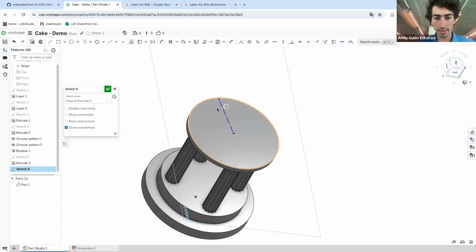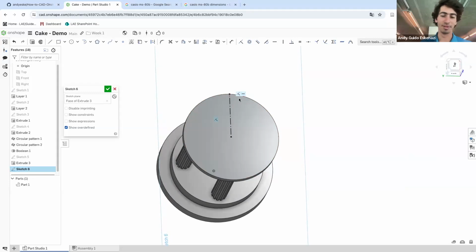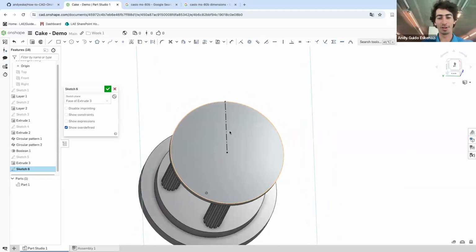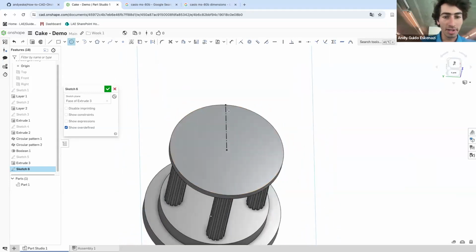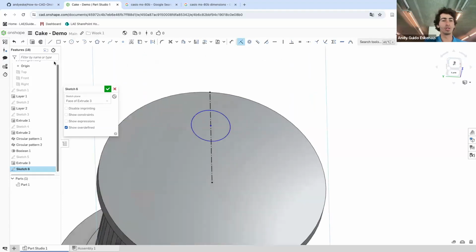Again, click on this point, letter I, click on that one. So now it's coincident. You can see how this point in here I can move all around. The one thing that is not defined is the particular angle. Oh, actually now it became defined, so now it's all vertical. In any case, I can bring in a circle. We can draw it there, for instance, and then again click on that point, letter I, and bring it to be coincident on the line.